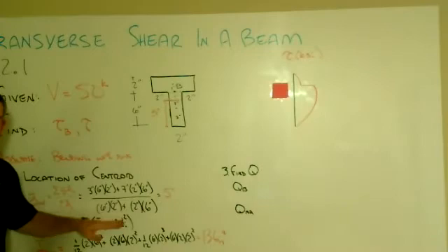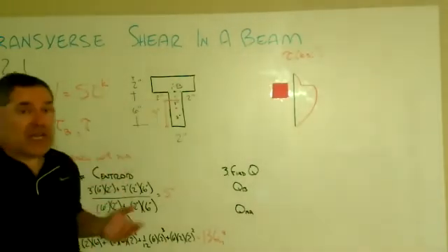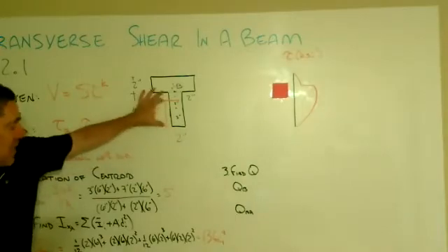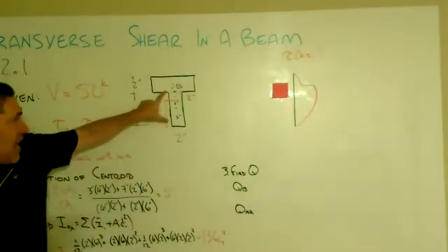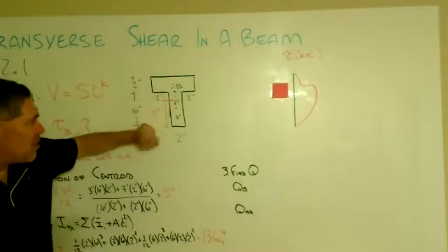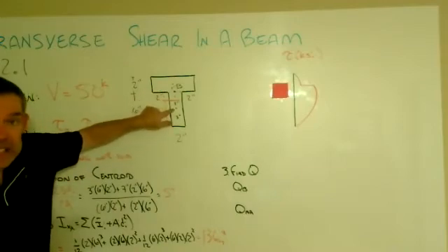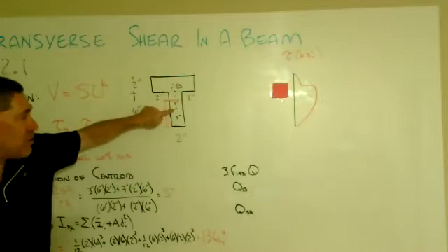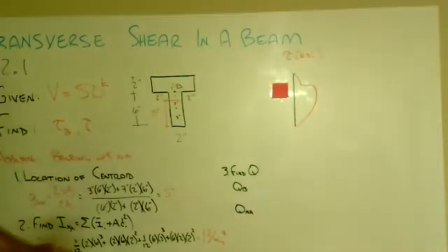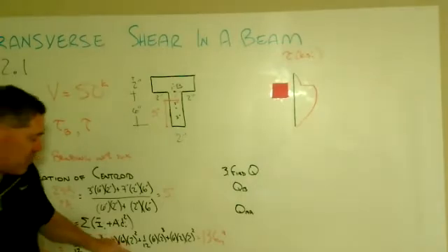Then we have to find the second moment of area of this piece. You apply the parallel axis theorem to do that. We have rectangles in both pieces, so 1/12 of the base times the height cubed, plus the area, 2 by 6, times its distance squared. That moves from its local centroidal location to the global one we want, which turns out to be 2 inches: the 5 minus that 3 from the bottom gives us that distance movement term.